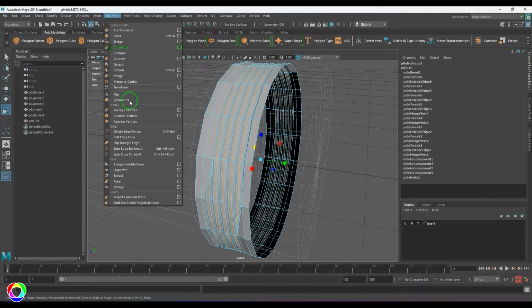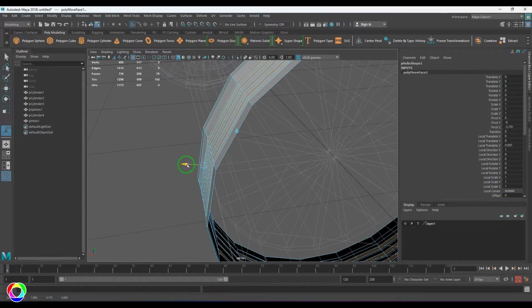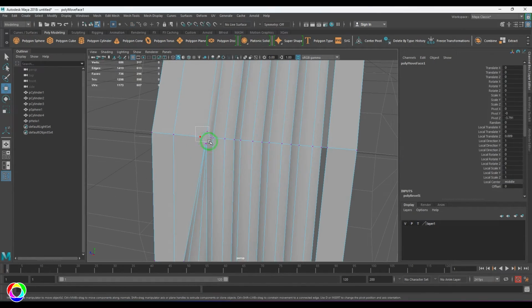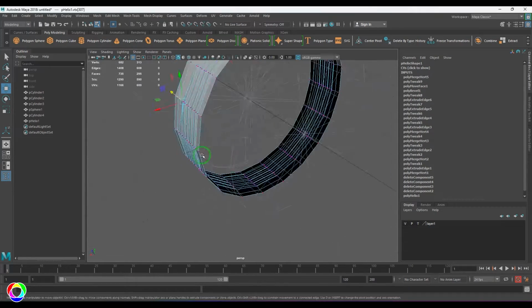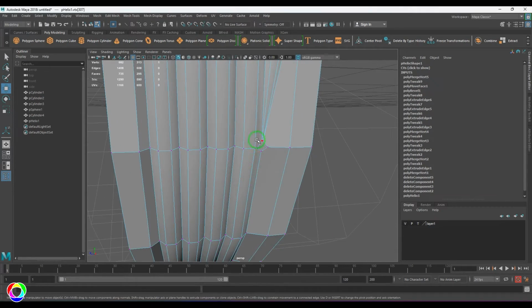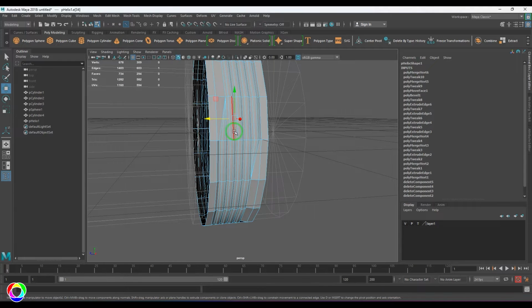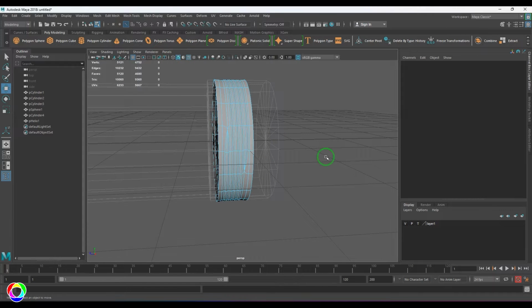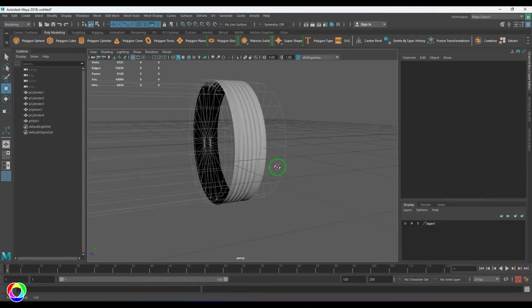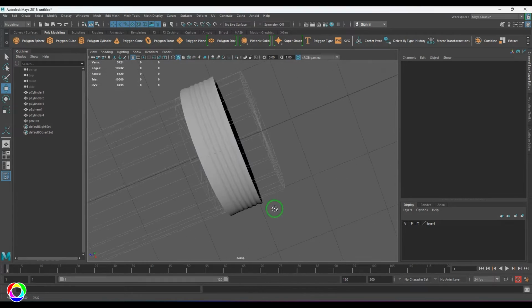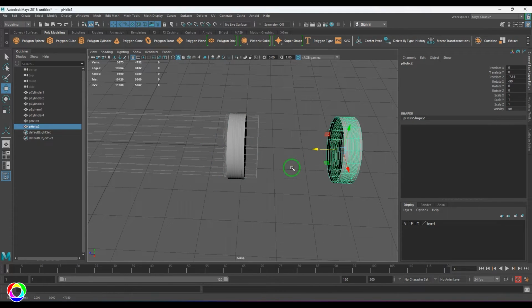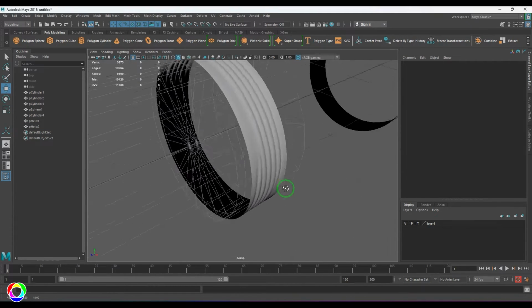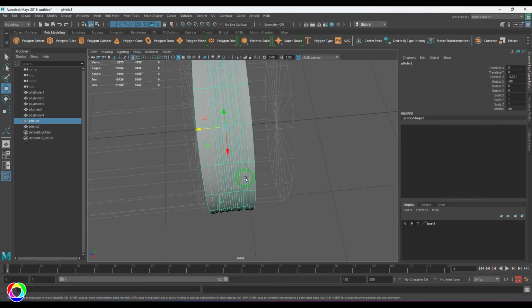Then I'm going to use the transform component tool, and then I'm going to merge those vertex points where this bevel has created a face, and then I'm going to apply a mesh smooth, and then I get this one. Okay, so that's pretty good, and I just wanted to keep that model, which I'm going to use again and again. So I've got that nice spiral cap effect.